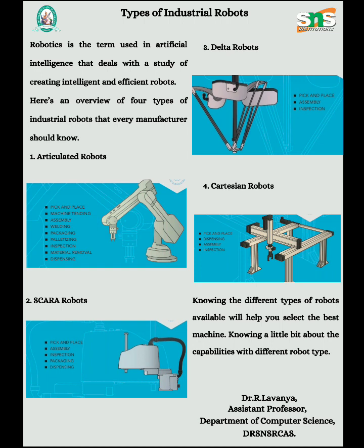It uses 3 base mounted motors to actuate control arms that position the wrist. The basic delta robots are 3-axis units, but 4 and 6-axis models are also available. By mounting the actuators on or very close to the stationary base instead of at each joint, the delta robot's arm can be very lightweight. This allows for rapid movement, which makes delta robots ideal for very high speed operations involving light loads.